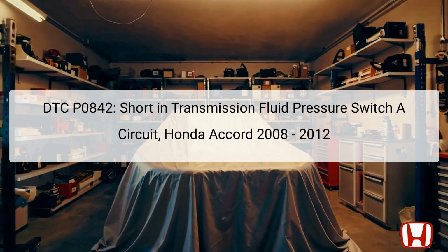The transmission fluid pressure switch plays a crucial role by monitoring the pressure of the transmission fluid, which is essential for proper shifting and overall transmission functionality. Its location is typically found on the transmission assembly itself, making it key in relaying information to the Powertrain Control Module, PCM. This DTC highlights an electrical circuit problem rather than a mechanical malfunction in the transmission. It's imperative to utilize the Honda Diagnostic System, HDS, to record freeze data and snapshots to ensure all relevant diagnostic information is captured prior to troubleshooting.